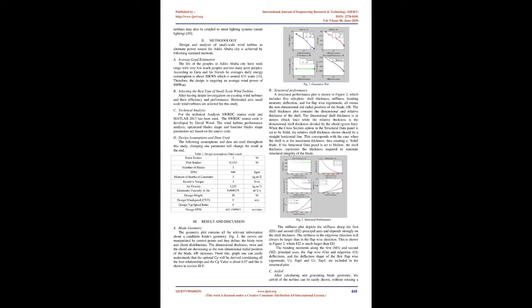Electricity output should be as sustainable as possible for off-grid applications. Therefore, wind turbines for off-grid applications should be optimized for low wind speeds so that electricity is sustainable, with the lowest possible cut-in and rated speed [9].